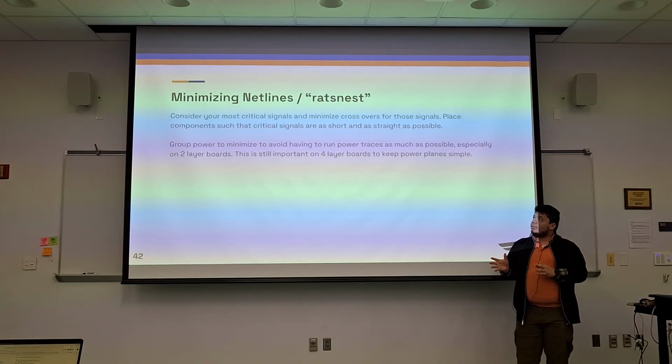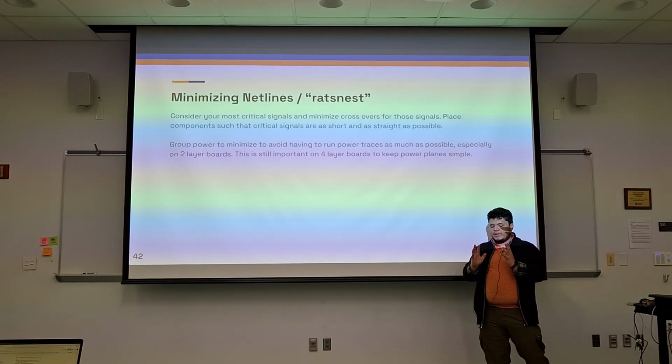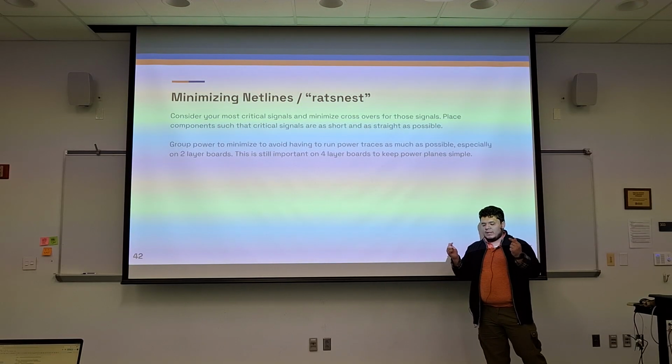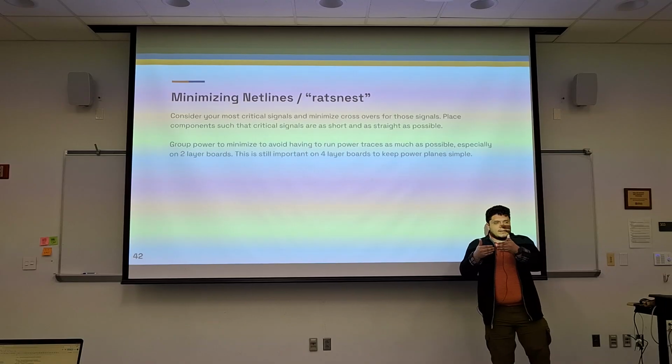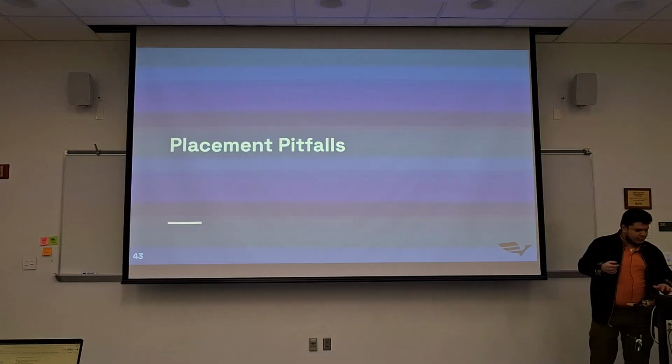So when we minimize the rat's nest, consider what is the most critical thing that needs to be the shortest, so our CAN bus, our SPI, and try to minimize that distance, even within functional groups.